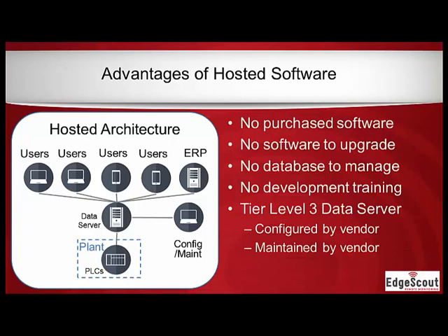There's no database to manage. A lot of traditional SCADA systems work really, really well for the first month or 6 months or maybe the first 2 years. At some point, the database continues to grow, and if there's not somebody actively maintaining that database, eventually your data collection system gets slower and slower, and your reports, trending graphs in particular, get painfully slow over time. Somebody's got to manage that database and keep it running efficiently.